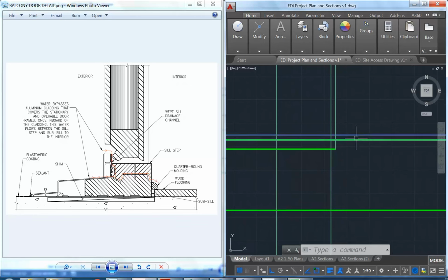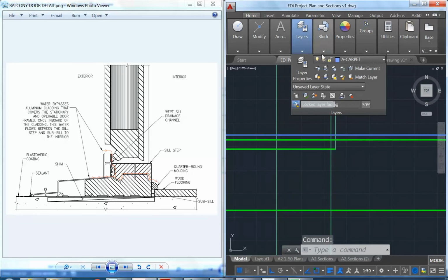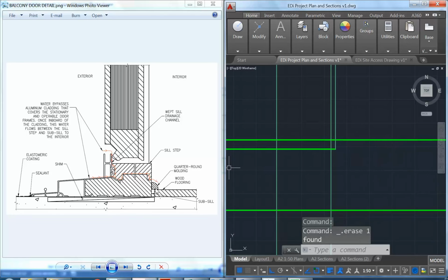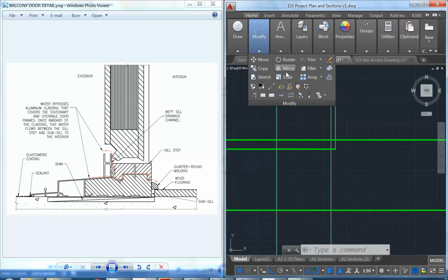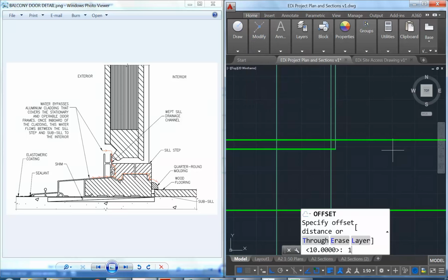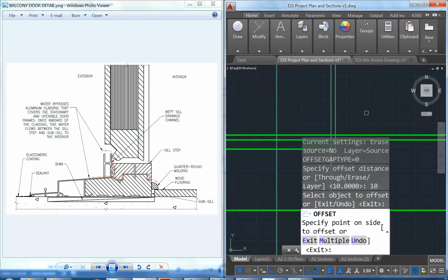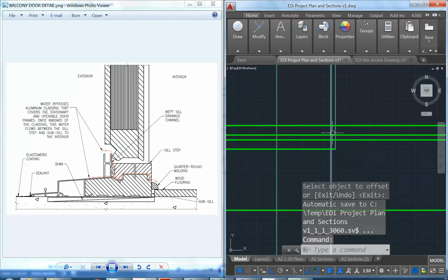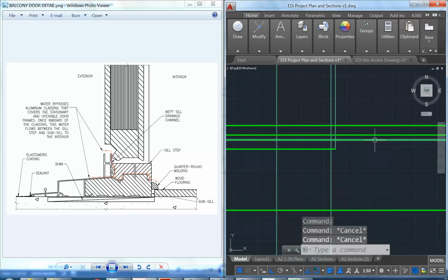And then we've got the line there that is the carpet, and that's in this case going to be replaced. Well, I'm going to go with this using wood flooring, so I'll just say it's a floating floor. And there's something not shown here that we should show, which is the underlay. So I'm going to add that as well. So I'm going to offset 10 mil. And you'll have to research this depending on the flooring system you use. It's really easy to look this up. All the flooring manufacturers will give you the sizes that they need. So there I'm going to assume 10 mil for the underlay, and then 20 mil for the flooring itself.